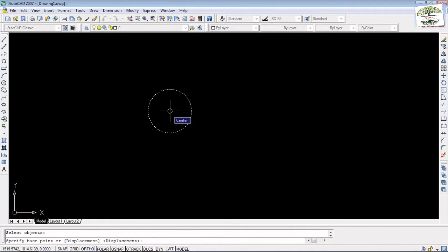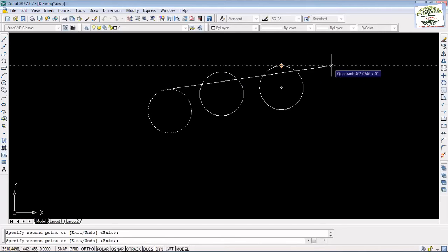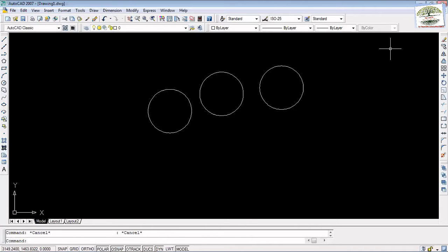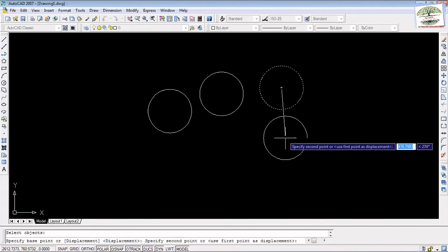It will ask you to take a reference point along which you will be copying the object. Let me show you. Copy, left click, I'm selecting this and left click again on the selection. When selecting an object, bring the square onto it, left click, and a dotted line will come. Then right click. Now I'll select the reference point as the center. Now see.